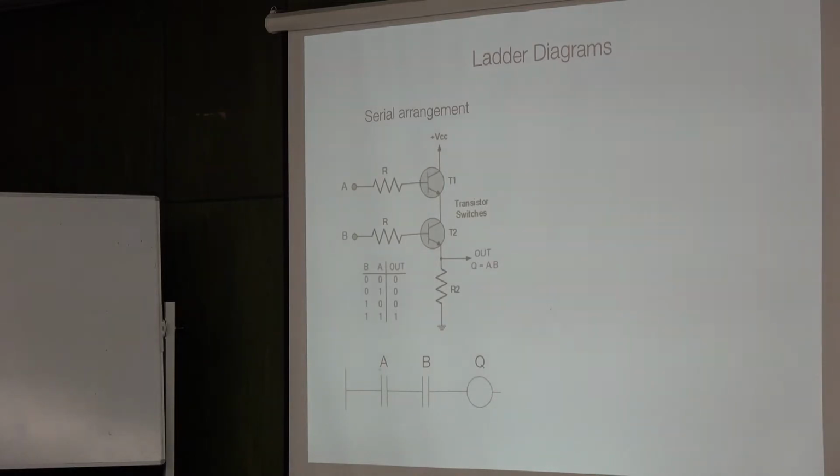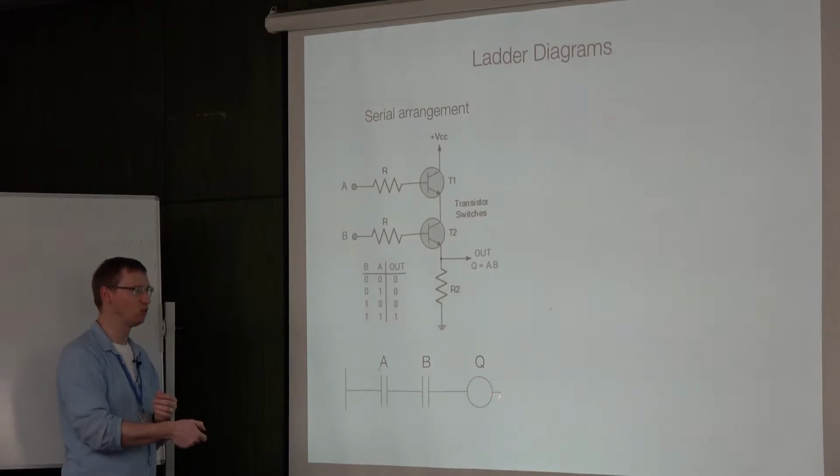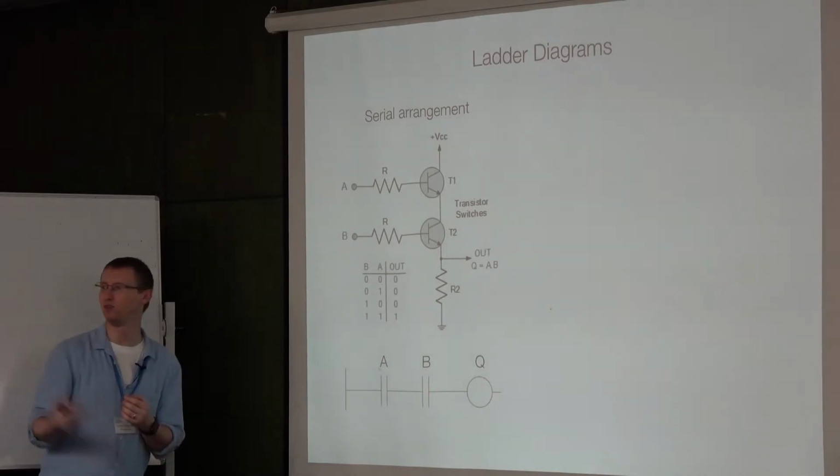Okay? So it's now all about how we should combine those basic building blocks together so as to represent the logic which we require. So let me just give you an example. You have a machine, say some kind of drilling machine, and you are only allowed to start up the machine when the gate is closed and maybe when some safety switch is turned on, just to make sure that it's safe to enable the machine. Okay? So obviously we would use a binary multiplication because we want to enable the machine only when the gate is closed and when that safety switch is enabled.